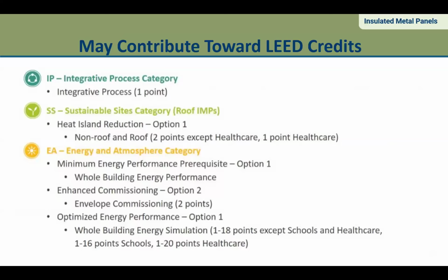On average, a building that features insulated metal panels, either as the primary cladding or the barrier backup system, is able to compress its schedule 5 to 7 weeks versus a conventional built-up assembly. That's mostly achieved through reduction in the mobilizations and getting material on site and working your way around the building.